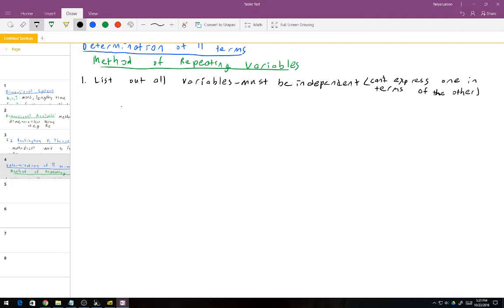So delta PL, we suppose that this was a function of D, rho, mu, and velocity V. There's a certain amount of guesswork at first to determine whether these are the only variables affecting the fluid flow. We could probably imagine other things as well, such as the roughness of the pipe, the surface material.